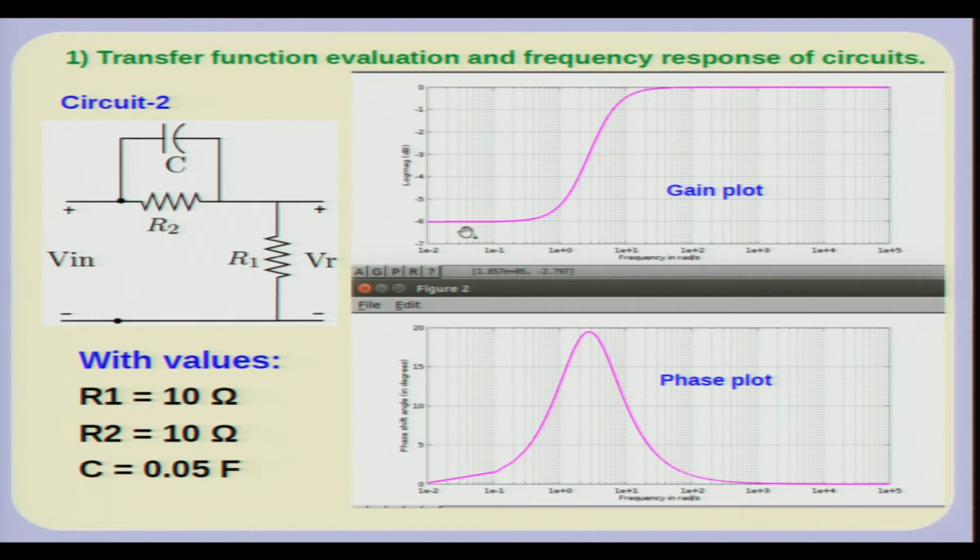The low frequency gain is also called a DC gain. So, you can specify the DC gain, you can specify the phase shift and what frequency you want it. There are 3 things you specify and you have 3 variables, so you can uniquely get the combination of R1, R2 and C to achieve this.